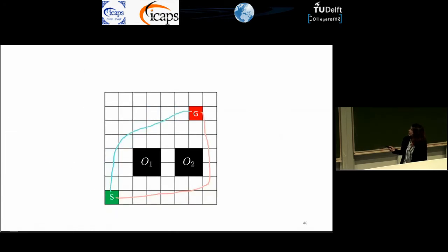So here specifically, let's say that we only provided this path, and this is the homotopy-based heuristic that we're providing. There are more details about multi-heuristic A-star that I didn't go into, but multi-heuristic A-star takes in an anchor heuristic, and this anchor heuristic is a consistent heuristic, in which case, if you notice, all the sets of heuristics we used had one Dijkstra heuristic, so that's the consistent heuristic we use. So if in this case we only provided this homotopy-based heuristic, there would also be one more consistent heuristic, and so eventually, also because A-star is complete, it will be able to find a path to the goal. Does that make sense? Yeah. Okay, thanks.